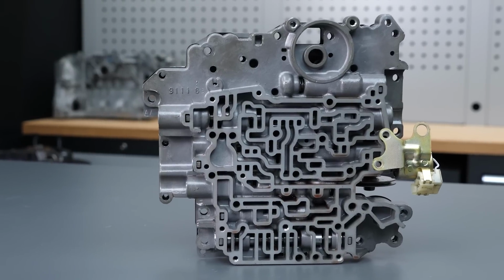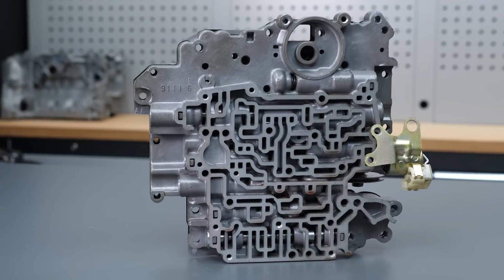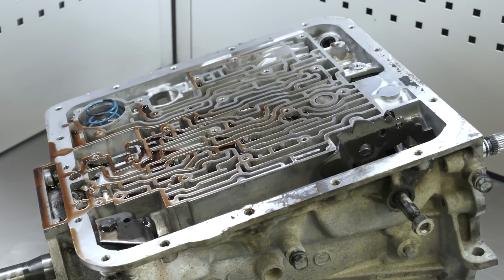The valve body delivers hydraulic fluid at different pressures to different components at different times as conditions demand. When we talk about pressure in the transmission, the first item we often reference is line pressure, which is the high pressure feed for any other systems that follow in the fluid flow path starting at the transmission pump. Because line pressure feeds other hydraulic circuits, such as clutch actuation circuits, we should avoid requesting pressures at downstream items like clutches which aren't feasible.